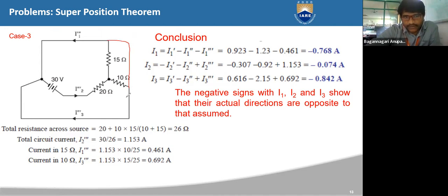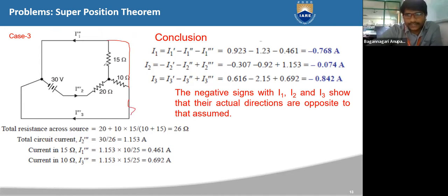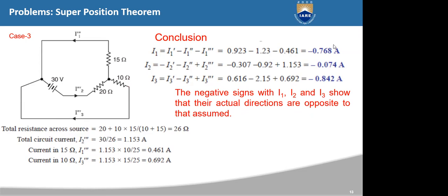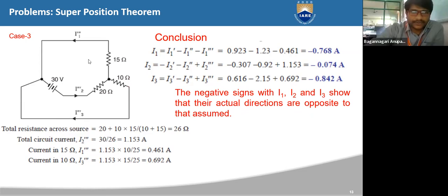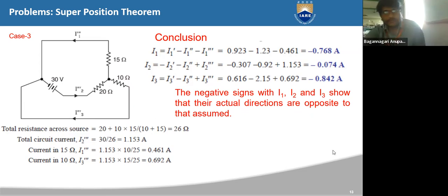Yes, sir, just shorting, right? Yes, so that will be clear. And see, this is a symmetrical circuit. You can apply the same principle that you have done for the first case. The assumptions we made in case one will be applicable for all the three cases, right? Okay, so this is how we calculate the values of currents using the superposition theorem for a star connected network.